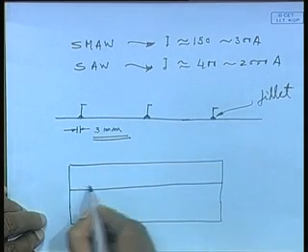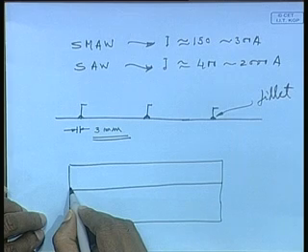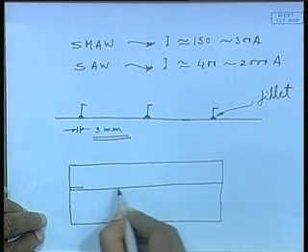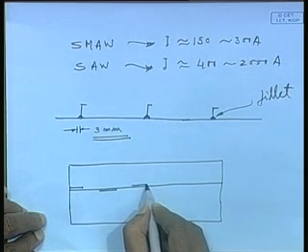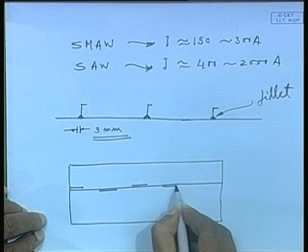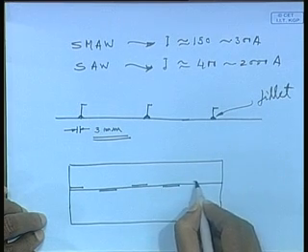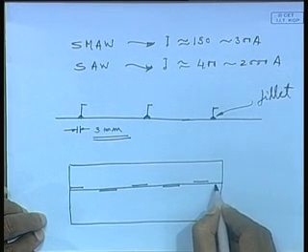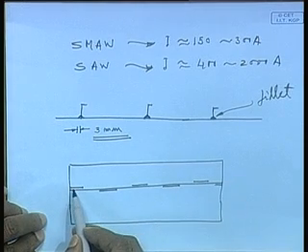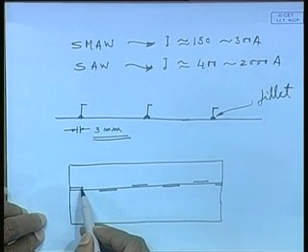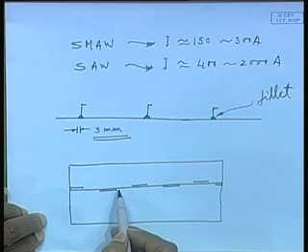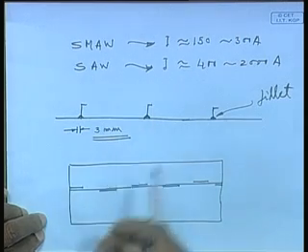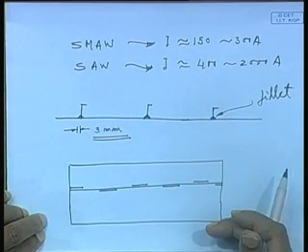instead of continuously welding on both sides, let us assume a situation I weld like this. These small lines I am drawing show the fillet deposition. So what I have done, this part only one side I have welded, then I have given a gap, then again on the other side I have welded, again a gap. It is just as if the entire welding you have staggered it.